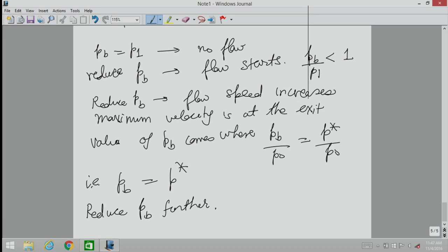The Mach number cannot become bigger than 1. In a converging channel, if we start with a subsonic flow, the maximum Mach number we can attain is 1. So if the back pressure is such that the Mach number there has to become bigger than 1, it will not happen. The flow in the channel will stay same.